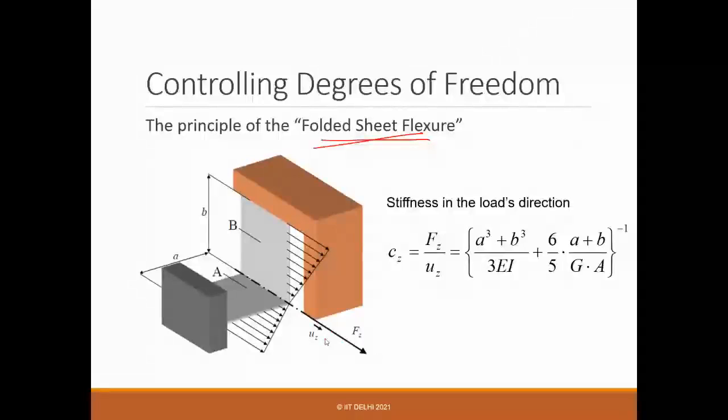Flexures are sometimes also used as a bearing, for small movement. What you see is floating, but there is no physical contact. And since there is no physical contact and only elastic deformation, you are free from any kind of backlash or virtual backlash, which you get because of the friction between contacting surfaces. But anyway, we'll discuss that again.